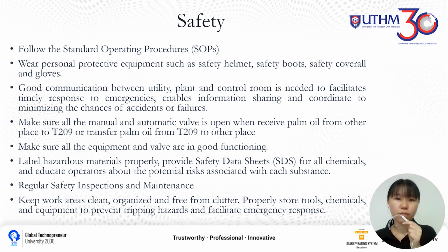Then make sure all the manual and automatic valves are open when receiving palm oil from other places to T209 or transferring palm oil from T209 to other places. Make sure all the equipment and valves are in good functioning. Label hazardous material properly, provide safety data sheets for all chemicals, and educate operators about the potential risks associated with each substance.